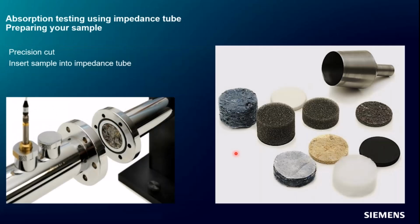Some considerations we have when using an impedance tube for this type of measurement. First and foremost is providing a precision cut. If you purchase an impedance tube that Siemens sells, it will come with one of these sample cutters that you can use.